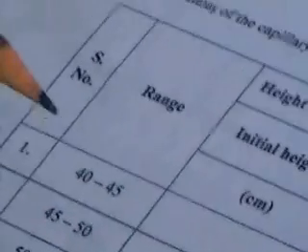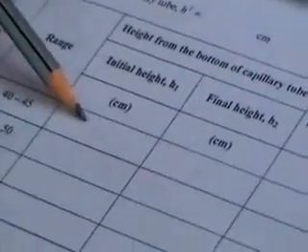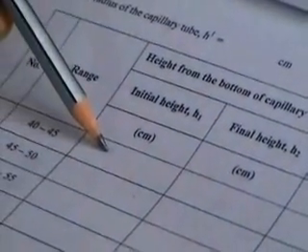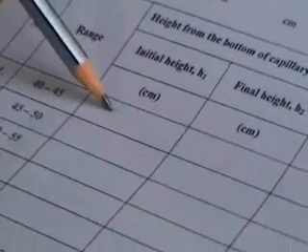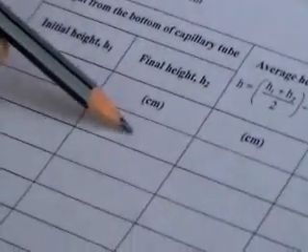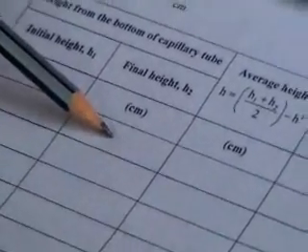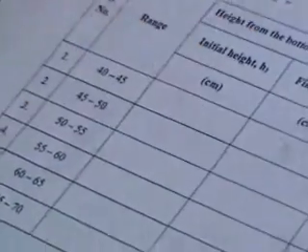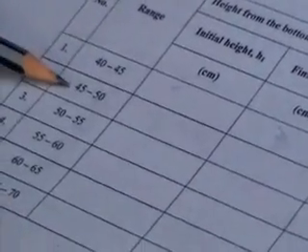So you have to note that value in these columns, that is, the range is fixed, in flowing from 40 to 45, you have to note the initial height. Height of 40, I have already told you, is 40 centimeters from the base of the capillary tube, 45 centimeters from the base of the capillary tube, and then subtract 2.5. Height of 45, that is H2, will be 45 minus that 2.5 centimeters. So you don't need to keep noting the height for all the values. 45's height automatically becomes 45 minus 2.5 here, and that value you can note down.